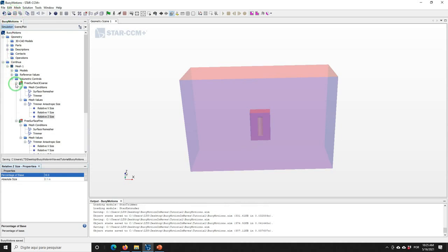In order to minimize errors in interpolating variables between the two meshes, the background mesh and the overset mesh, we need to use the same order of magnitude of grid density in the overlapping region of the overset and background meshes. To achieve this goal, we're going to set up another volumetric control at the overlapping part of the two regions. So let's first create a geometry part here.